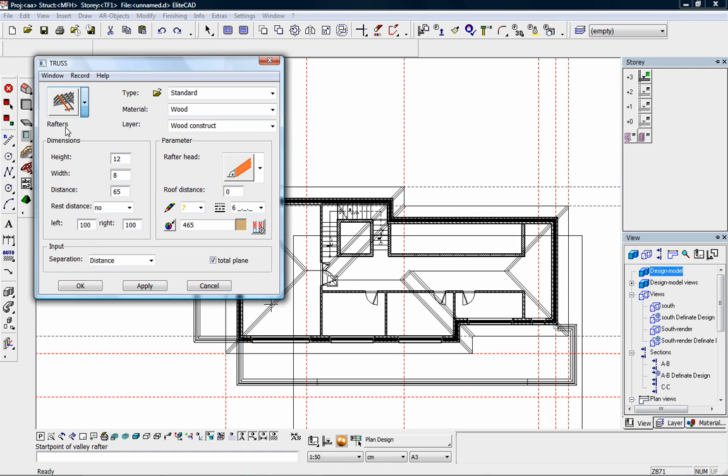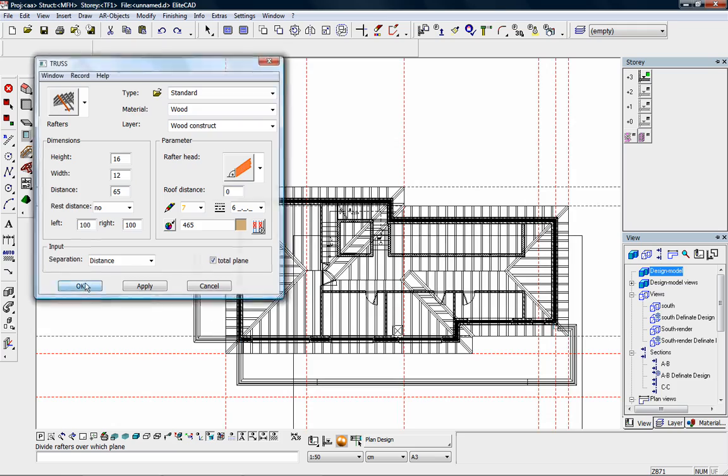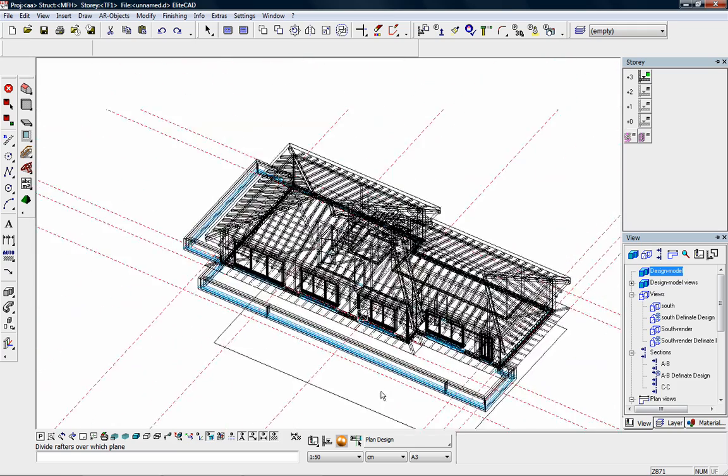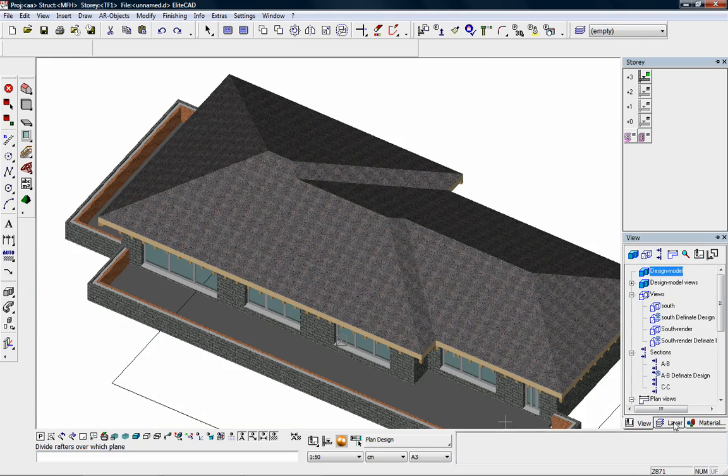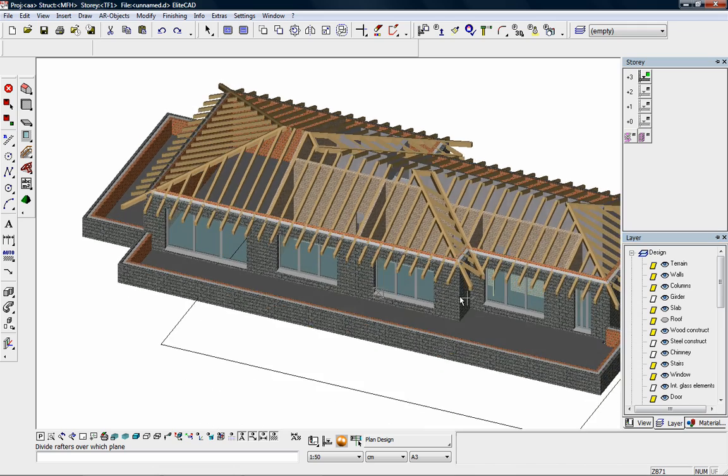We would also like to show the distribution of the subsidiary rafters. Here we define the distance between the rafters, their length and their height. Now all we need to do is click on the individual roof sections, and in so doing, the common rafters have all been distributed around the roof. Peering into the drawing can show us exactly how this possibility has been achieved.